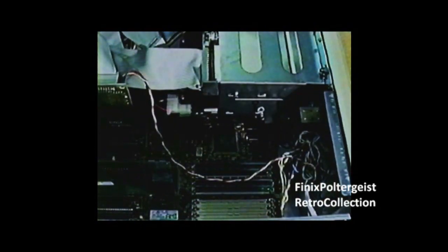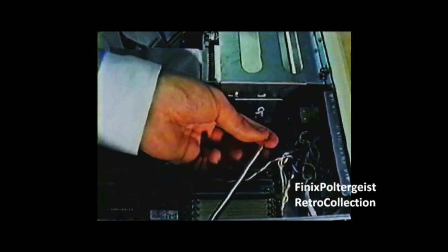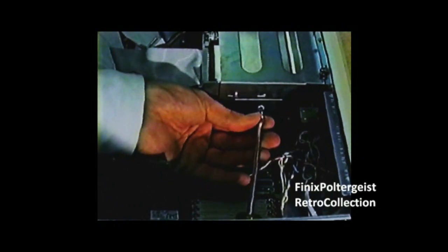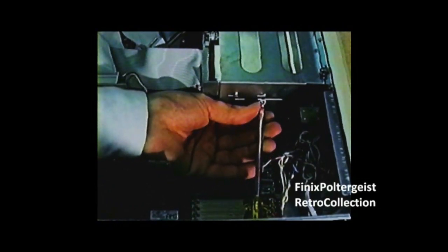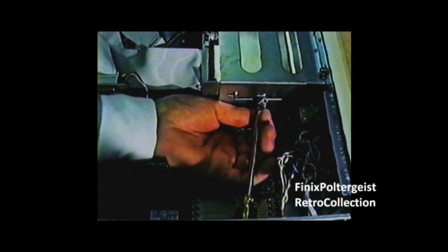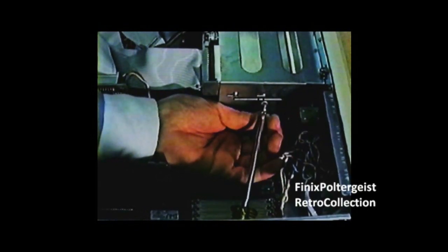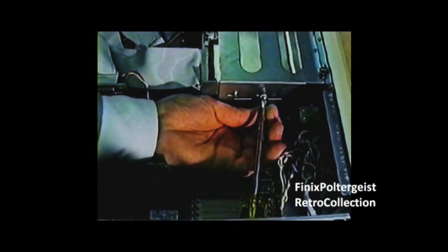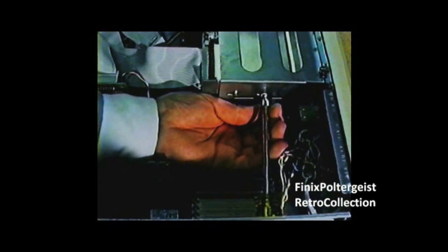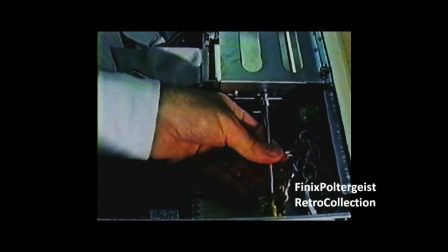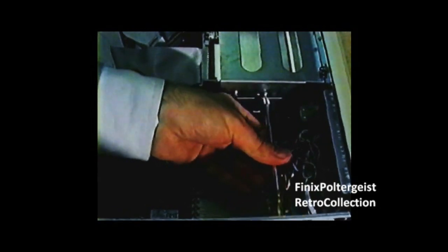When all necessary cables are connected, it is best to tie them together and fold them neatly. Lastly, ground your system by attaching the ground wire to the case. The battery for the internal clock for this motherboard comes installed and is rechargeable. If your battery is different, connect it to the motherboard and secure it in place.